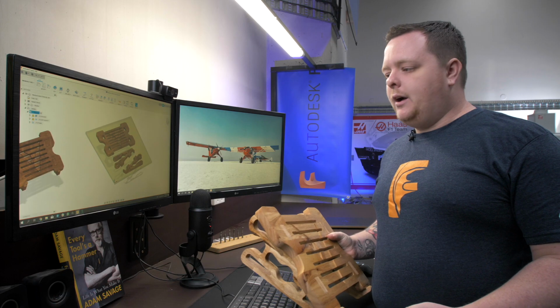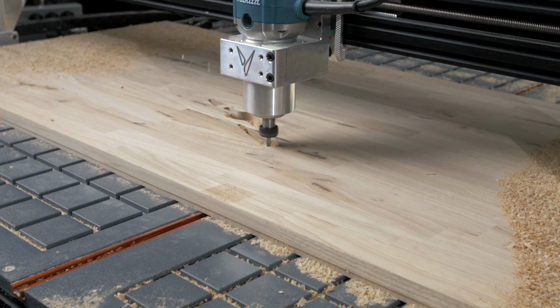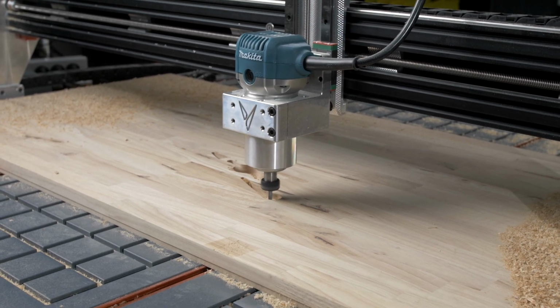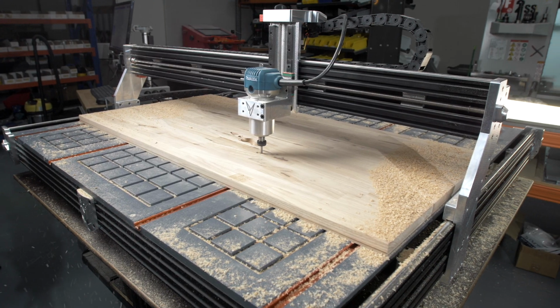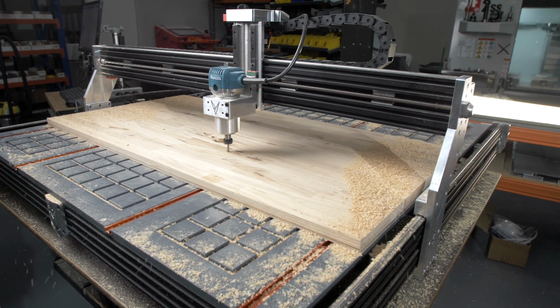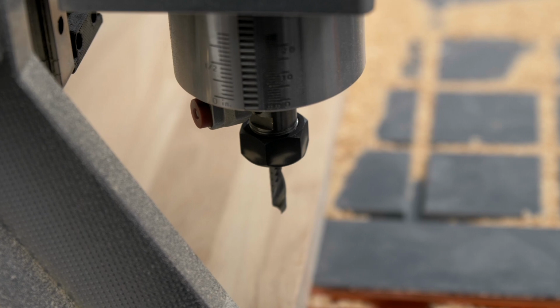So the last thing to do now is to post-process the toolpath and to send it to the machine. Now, one thing I'd highly recommend, if this is the first time running that program, is to post-process just the individual toolpaths by themselves and run them on the machine. That way, if there is any issues or you do need to make any changes, you have the opportunity to do that without having to basically come in and remake the whole thing again.